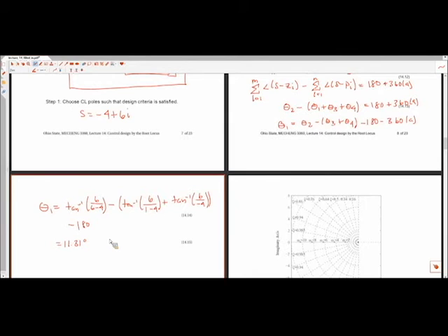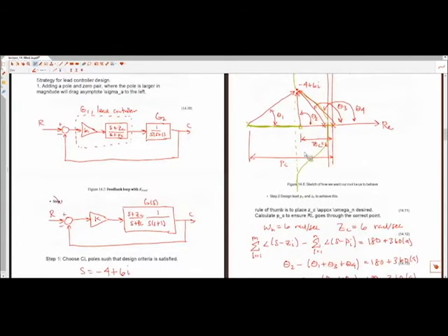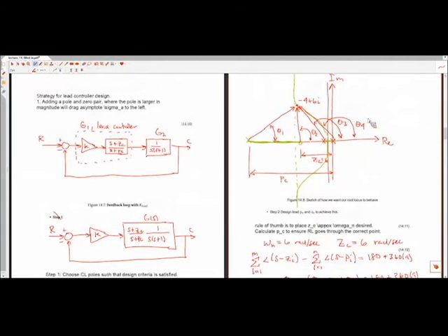Okay, so just kind of going back to what we did, very first homework in lecture 2, we talked about why you should be using the ATAN2 function in your calculator or in MATLAB and not ATAN. That's because the arctan function will only output phase angles between +90 and -90. So you need to provide basically the sign on both the real part and the imaginary part to get this correct.